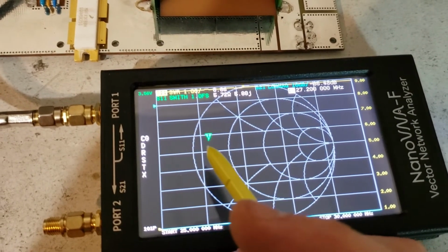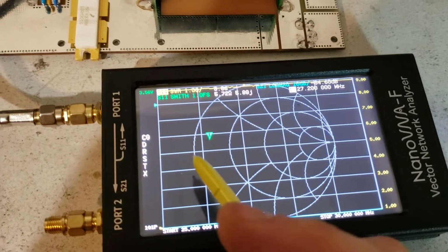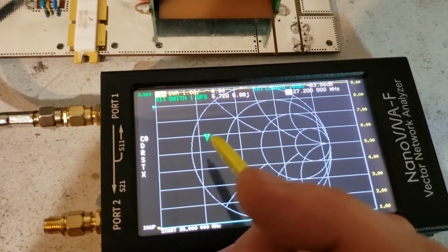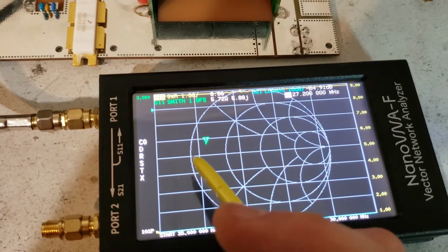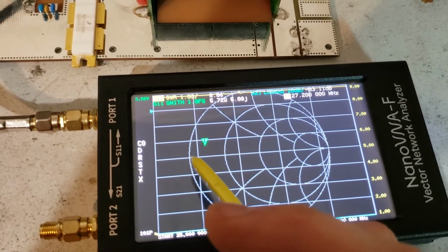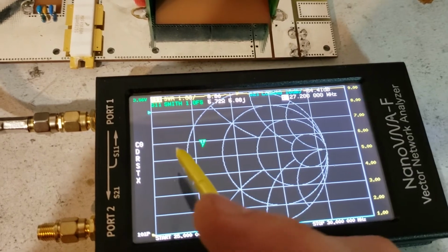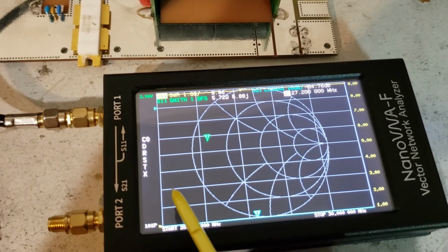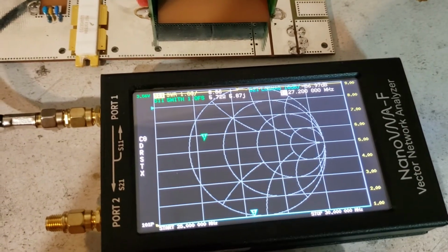I'm just stating some of my limited experience on that matter is 1 to 3 ohms for a Toshiba or whatever. So you're going to want to start probably on the higher end of that. Don't be afraid to start up at 5 ohms and then work your way down. That's generally a pretty safe technique, is to start high and work your way down until you get into a reasonable power output range with reasonable harmonics and all that kind of stuff.